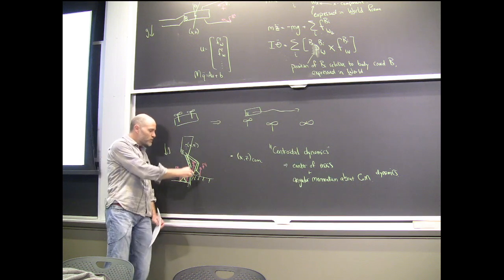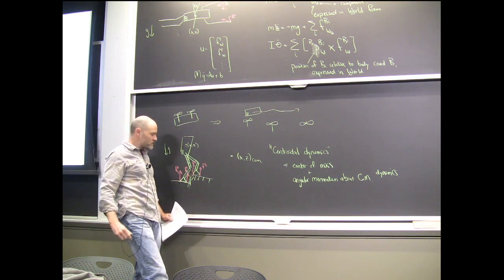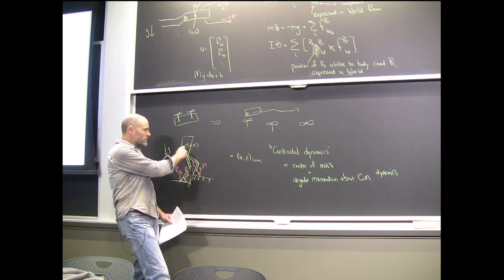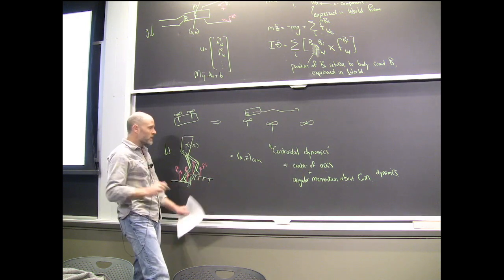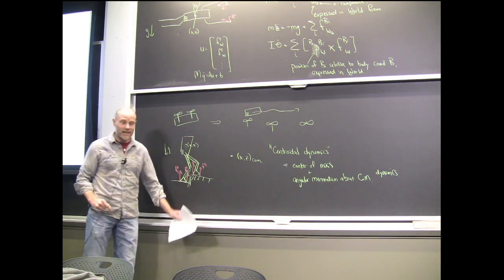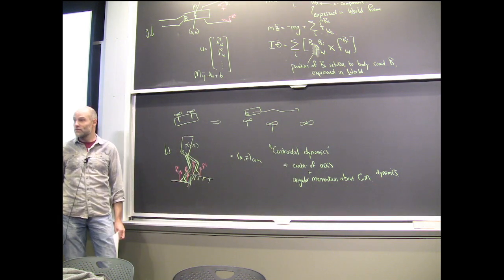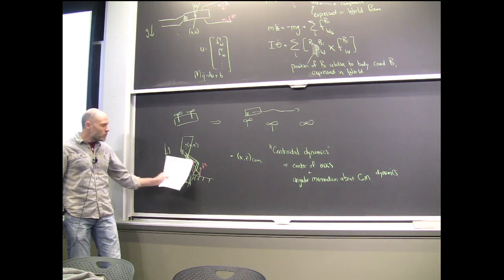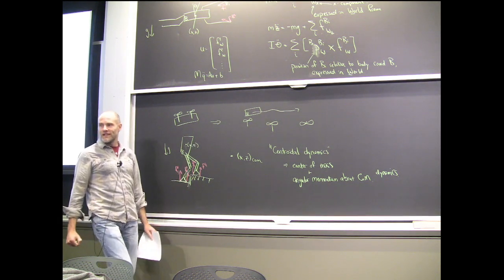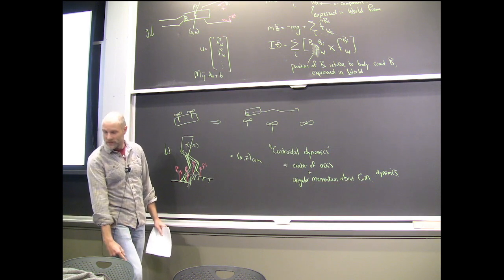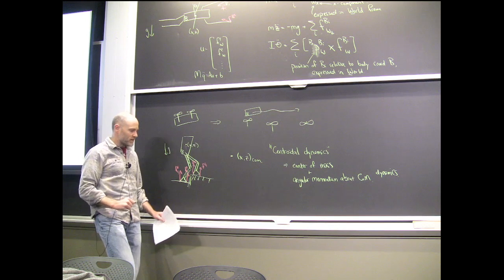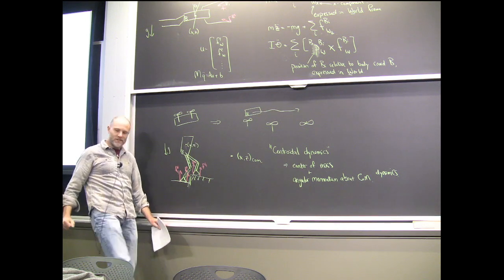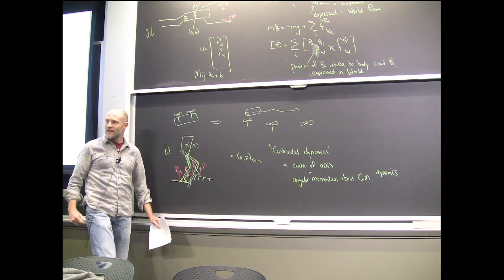So if you can choose your potential footsteps and the corresponding ground reaction forces, then you can plan a center of mass and angular momentum trajectory without worrying exactly how you got there, right? As long as I know that I could find a set of joint coordinates that would get me there, for any possible foot positions relative to my body, the details I can figure out later.